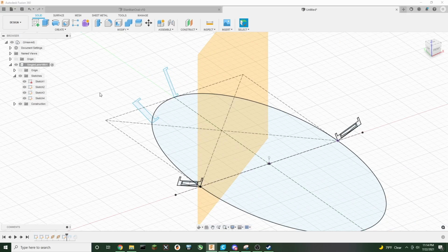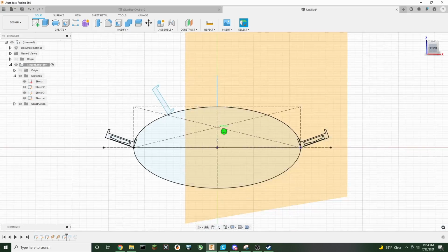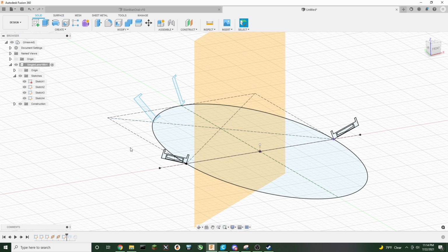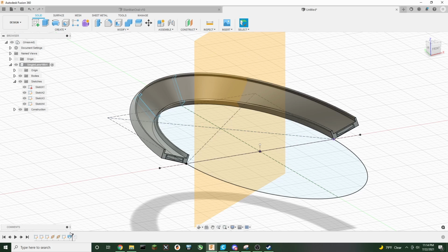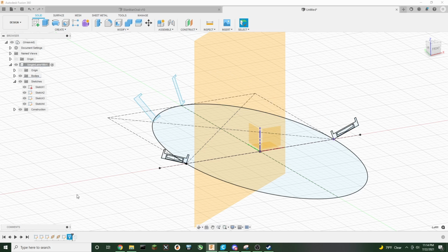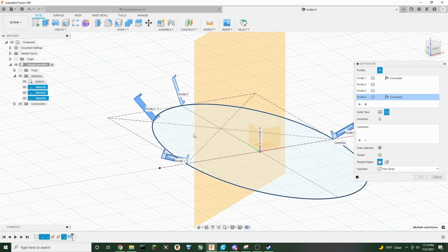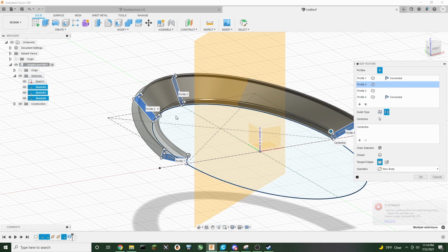So now if we have our back sketch and that sketch, we should be able to create a loft. So if we move forward, now we can actually edit that, and we can add this guy into here. Our lofts are out of order, so it doesn't know what to do. We're going to say, hey, this is 2, 3, 4.